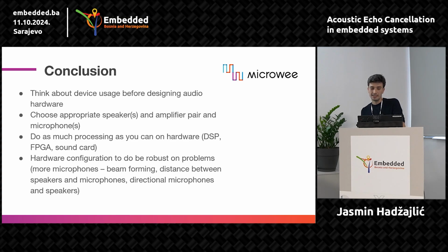Also, using WebRTC, PulseAudio CPU usage went to about 80% or 100%, that's like 1 of 4 cores on our processor, and that's too much processing power for something that's not the main thing. So do as much processing as you can on hardware, either using a DSP, some specific FPGA, or a sound card with integrated acoustic echo cancellation.